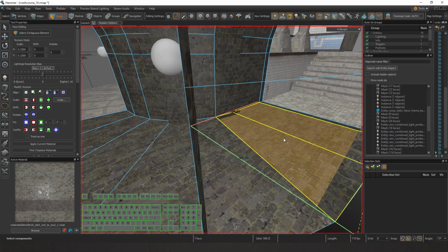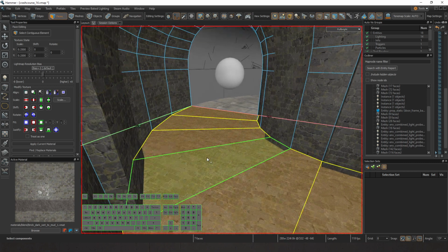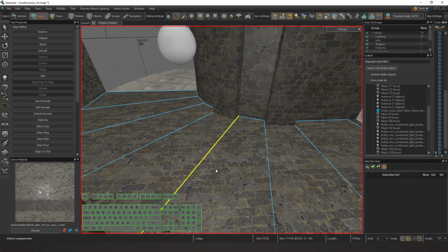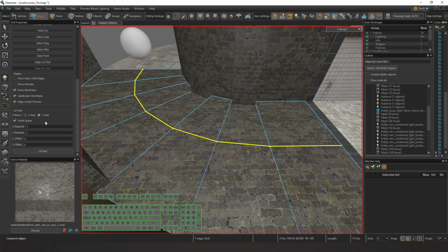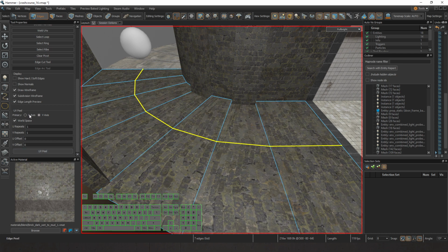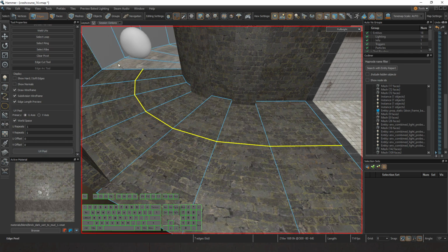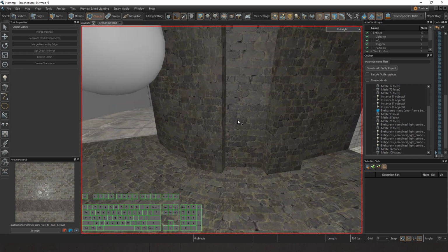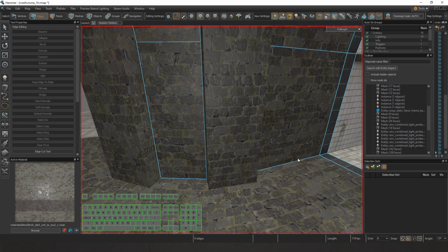Okay, so coming over here, I'm going to select our wall. I'm sorry, our floor. I'm going to press Alt N. I'm going to make it its own separate mesh. Press G after I select an edge, V, and let's peel this. Let's do it around the U axis. There we go. Now you can see it's curving towards that. And since I've separated that mesh, this is going to be separated as well.